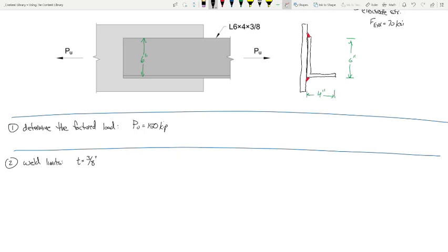Now this is in Table J2.4. What is our minimum weld size going to be? Remember, we need enough of a weld to avoid the heat sink effect. So what is that for a plate thickness of 3/8? Maybe 3/16. 3/16. All right, that's a min. A max is going to be what? Is it the thickness or the thickness minus 1/16? Minus the 1/16.